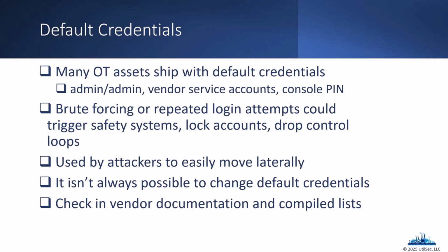But that means, what if that environment never changed the default password and you find that Click PLC online? Well, a quick Google search, if you didn't know the default password, will tell you it's Click. Try to log in with Click, and boom, you're in, because they didn't take the time to change the password. I can understand a lot of times they don't want to, because that could cause operational issues down the road. What if somebody changes the password and then forgets it? Or what if that person wins the lottery and no longer works at that factory?